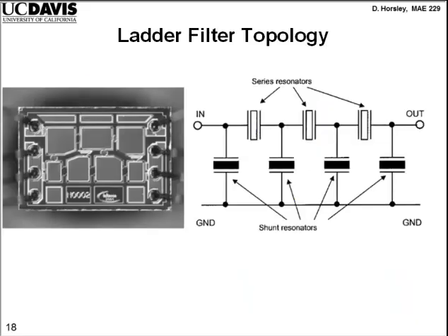Okay, and so for example, what's called a ladder filter looks like this. It looks like a ladder because it has some rungs on it. So here's the input signal, here's the output signal, and each of these little pictures, this symbol that people usually use for quartz oscillators, is equal to 1 mechanical LCR.